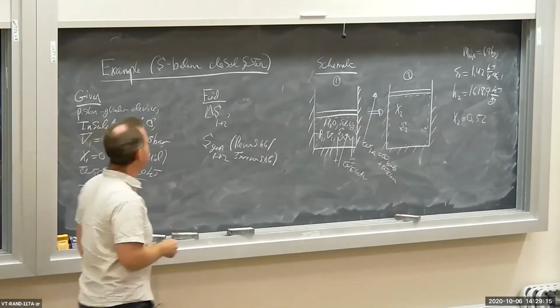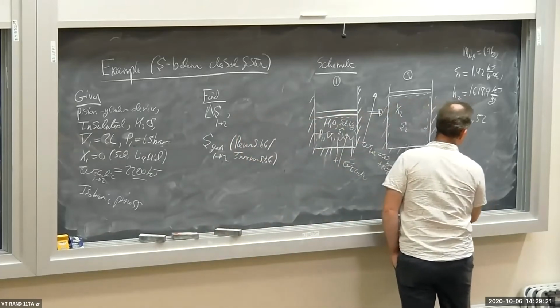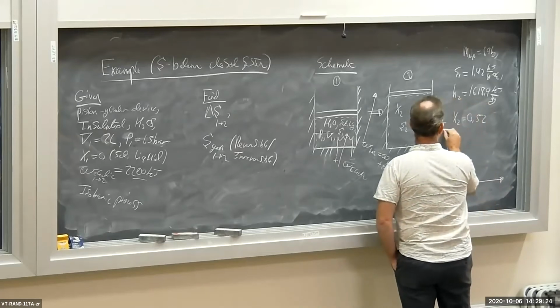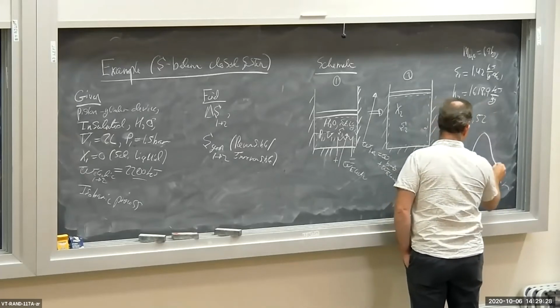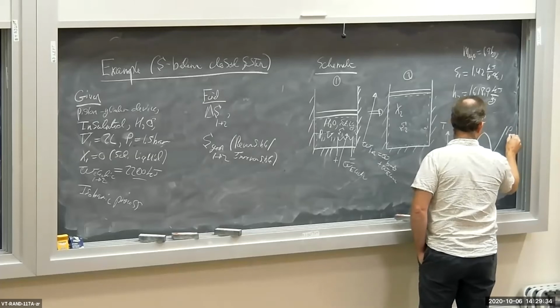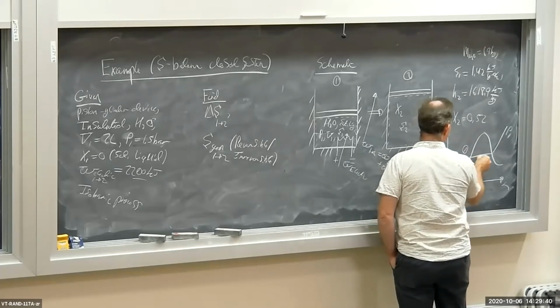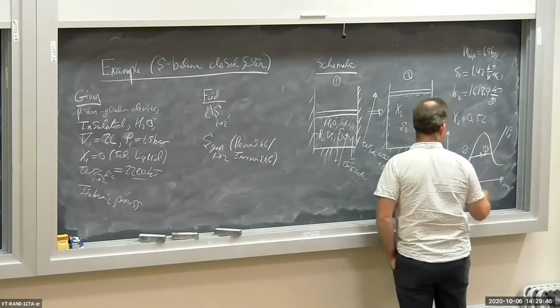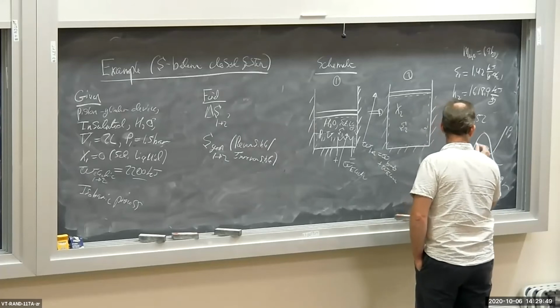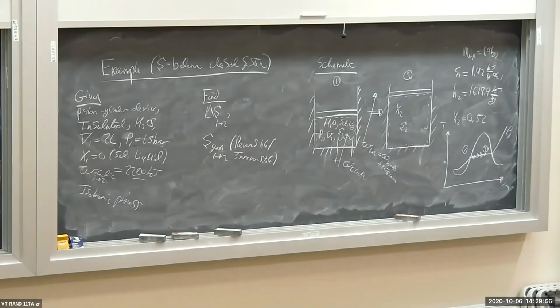By the way, let's put up a T-v diagram here so we can see what's going on. T-v, here's the saturation dome. Here's my 1.5 bar isobar. So we start off at a saturated liquid and we move to somewhere inside the dome. So there's state 2 right there, okay? There's the dome right there. So that's the process going on, isobaric expansion. Okay, so I got the quality at state 2.